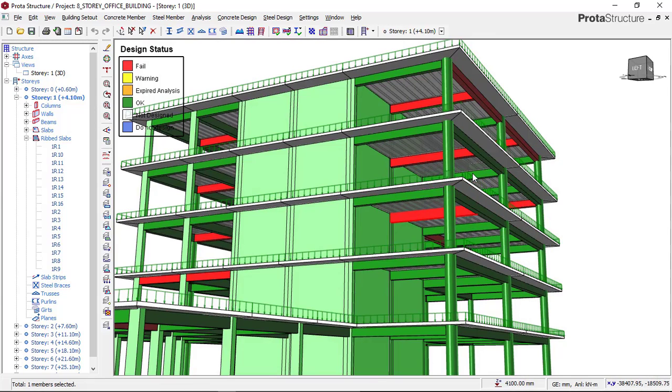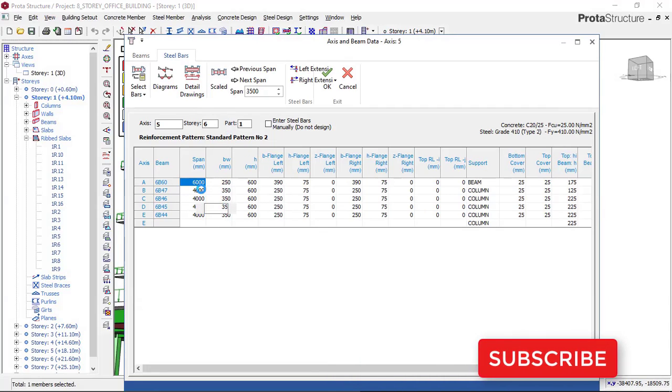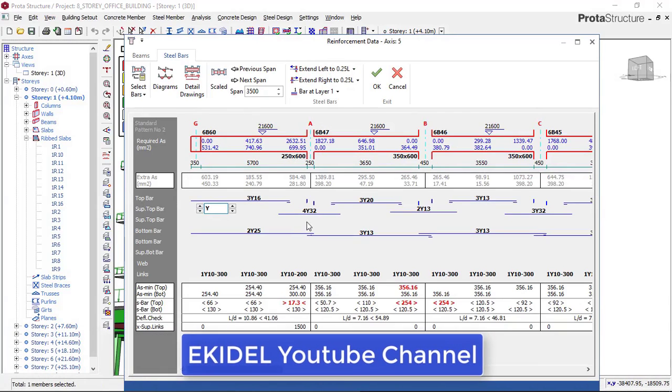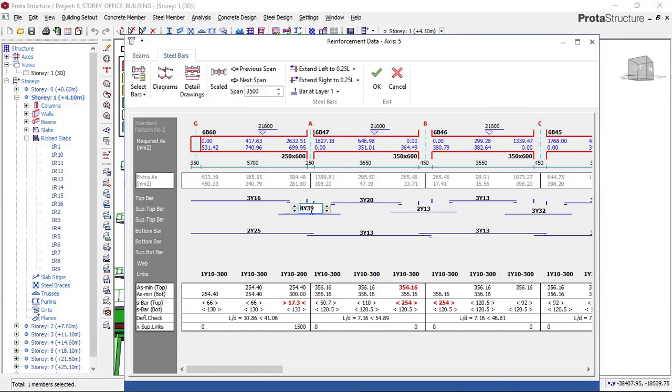Okay, so I'll check on this again, and then go and check on the members failing. You can see that this is not okay, that this diameter of 32 is too big. I would say that you should never use a diameter of 32 for a building, except you're building up to a 20-story or 15-story building, then they can begin to use diameter 32. But for a normal building of at most 10 stories downward, I would say that you should stick with diameter 25.